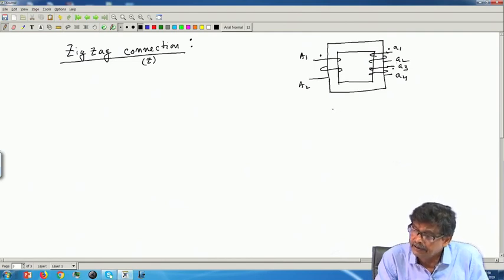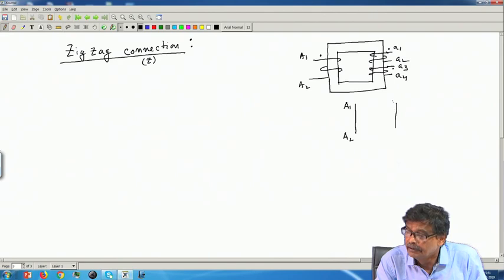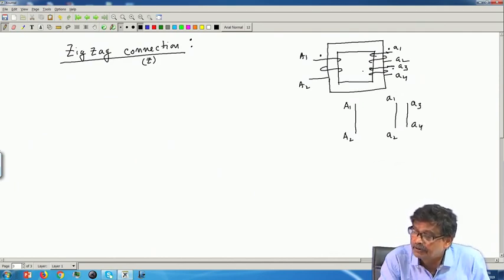Naturally, if you apply a voltage phasor, if the voltage is applied in the primary across this transformer A1 A2, on the secondaries you will have 2 separate but equal length phasors, because their number of turns are the same, N2 and N2, and this is N1.